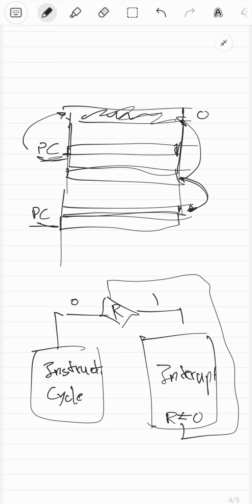And that's a problem, because now this thing is stuck in this process where it goes there, it reads all of this, and then it goes to, oh, what is this address? Oh, this is this address. It goes there, and then it does the same thing. So it's stupid, basically. That's what I'm saying. So don't do this. Don't let the user interrupt when it's running the code for the interrupt. And so for that to happen, you also set the enable to interrupt to 0, right?